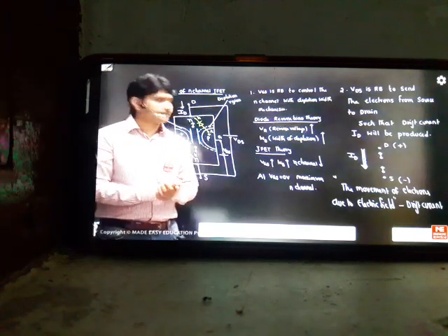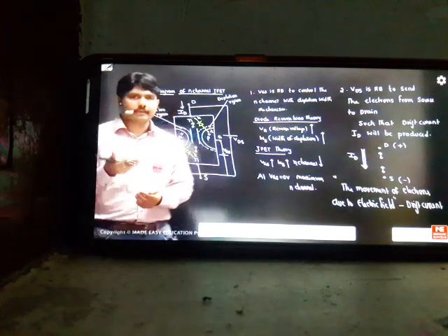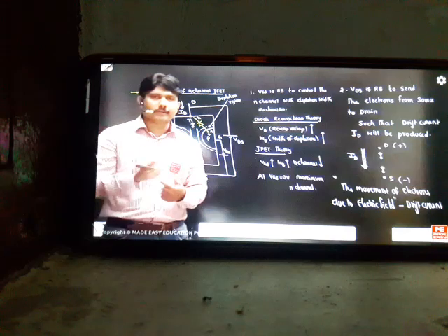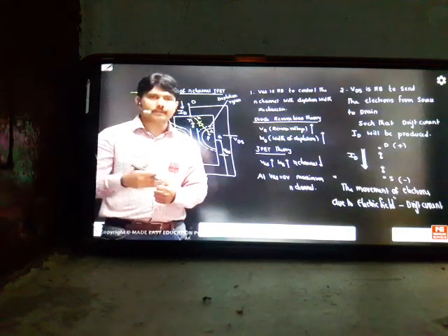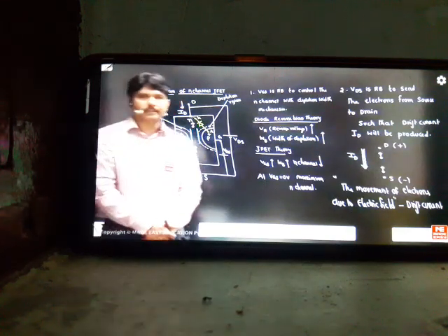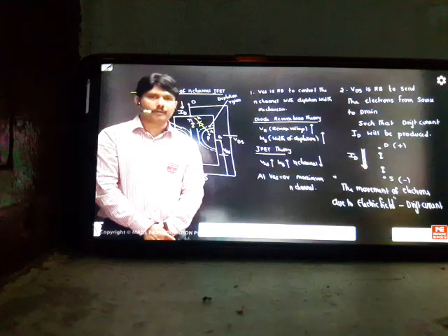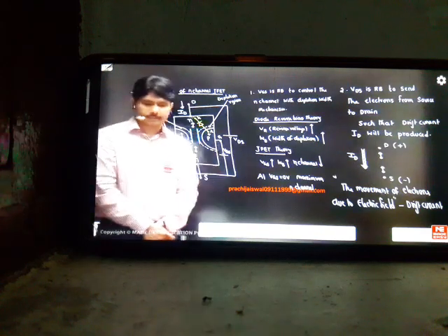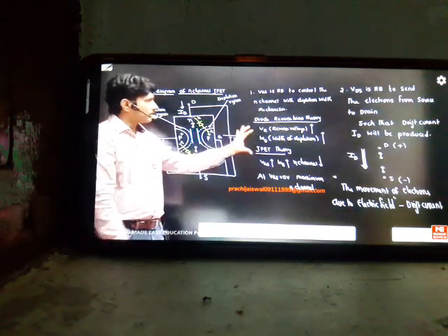Yes, Jahnavi, what you said is correct. On the source side we apply more negative, on the drain side we apply more positive, electrons will repel from the source, and you will get more current. That means you have to apply more VDS voltage such that you get more and more current in the device. Okay, VDS is meant to get the drift current. The more VDS you apply, the more electric field, and you will get more and more current in the device. Okay, so this is the story about the first topic and second point.